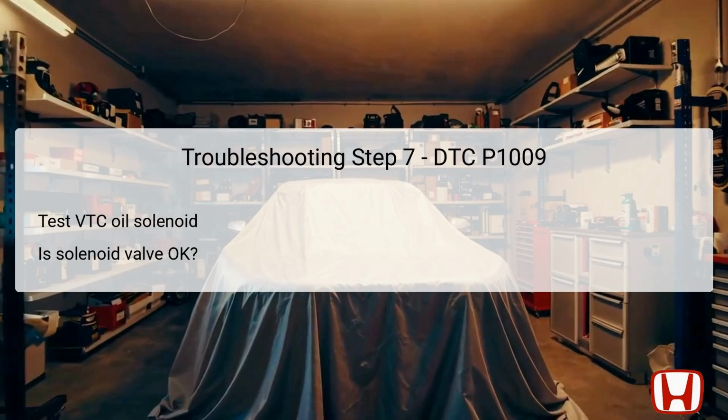In this step, the VTC oil control solenoid valve must be tested to confirm its operation. The solenoid valve directs oil pressure to the VTC actuator, and a malfunctioning solenoid will lead to incorrect oil flow, potentially causing timing issues. Testing involves applying voltage to the solenoid and observing its response, often using the HDS to monitor engine data simultaneously. If the solenoid is functional, you can move on to the next steps. If not, it requires replacement.